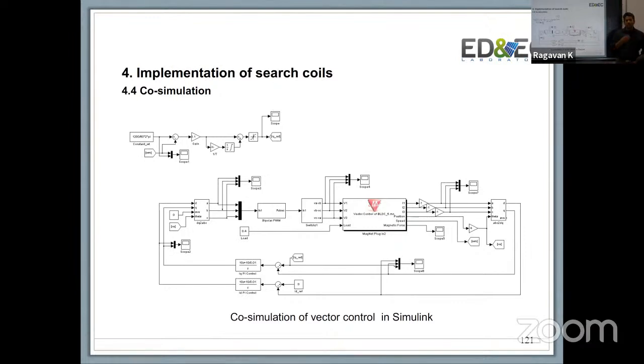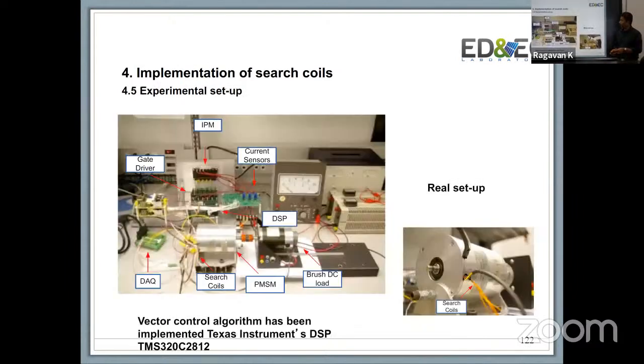As you noticed, as I was talking to you guys yesterday, we switched over from having an actual FEM model here for co-simulation to replacing this with a behavioral model. That made the system much faster. But the idea was still the same. We didn't want to decouple the behavior of the machine from the power electronics, because here we are sensitive to frequencies. We want to know what frequencies, if any, are being pushed out.